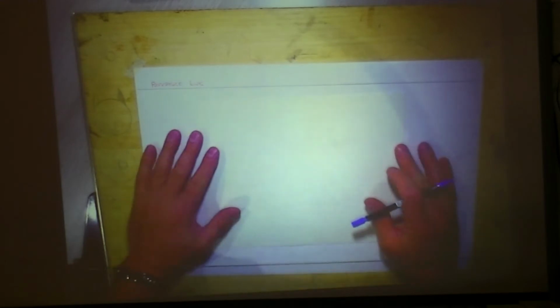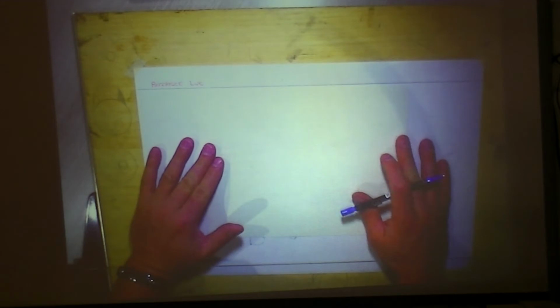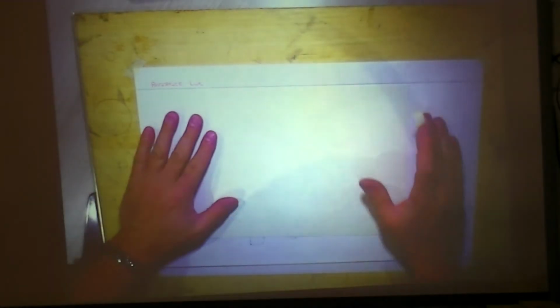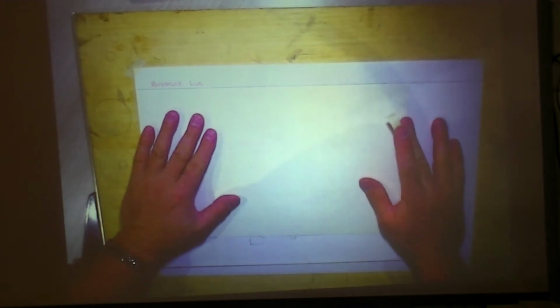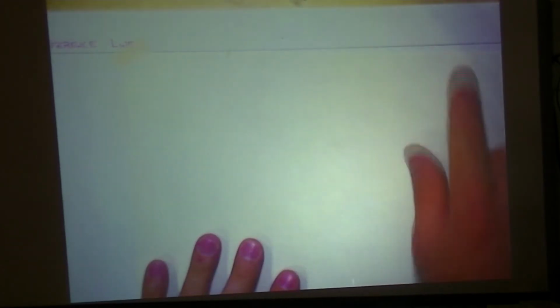Okay, so just like the backing sheet, you're going to use the reference line to line up the A-size sheet in a landscape orientation. Once you line it up, you're going to use a little bit of tape to tape down the first corner. And then you go through, again, checking to make sure that it's lined up with your reference line or the T-square.